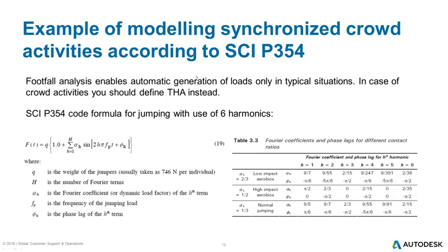Let's focus on some examples now. First, I'd like to show something related to the topic of the previous webinar. As you already know, watching it, footfall analysis can only be used for some typical situations, being mainly a single person walking. If you, for example, want to simulate behavior of a crowd, you need to use time history analysis